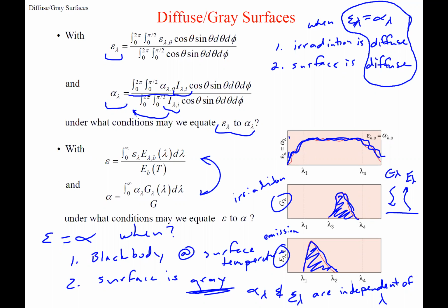it's at different ranges of wavelengths that it's irradiation versus emission. But if we look at the properties here between the lowest and the highest, so we look between this one and this one, 1 and 2, and between 3 and 4, we see the emissivity is equal to the absorptivity. Even though they're occurring at different wavelengths, over different wavelength ranges, that is a gray surface, okay? Let's give an example where it isn't. Let's say this emission was occurring here instead over this wavelength, okay?